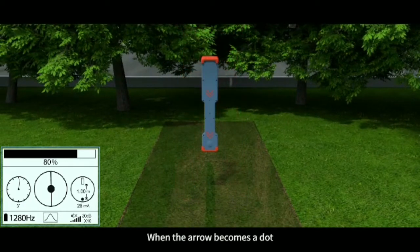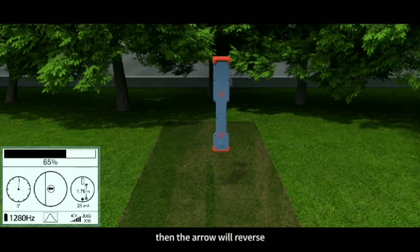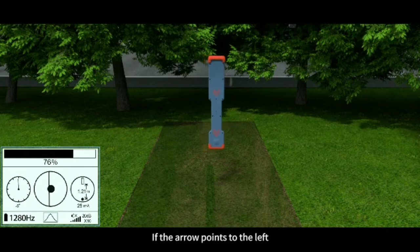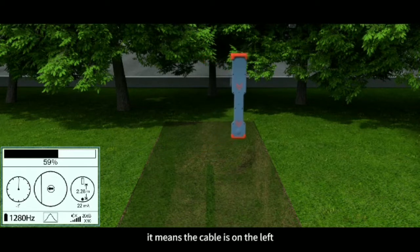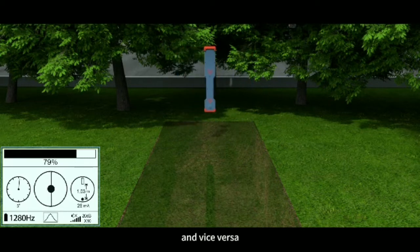When the arrow becomes a dot, if the receiver swings from side to side, then the arrow will reverse. Now the receiver is directly above the cable. If the arrow points to the left, it means the cable is on the left. The receiver should be moved to the left, and vice versa.